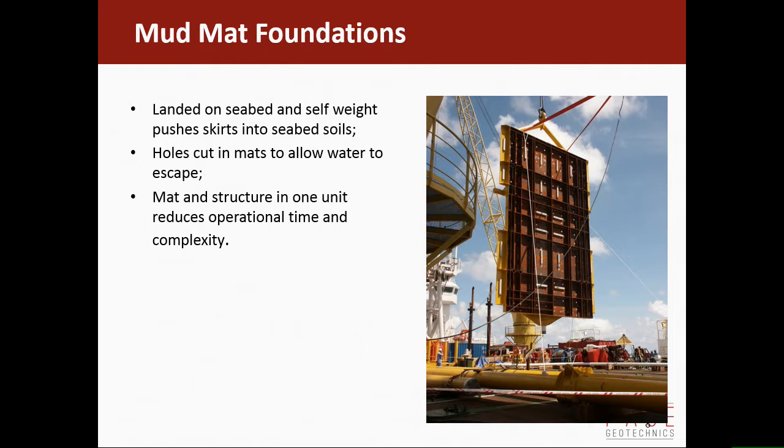that's an example of a mud mat foundation. That was a manifold we did, and it grew arms and legs. I think it went from 40 tons to 80 tons, and getting that to work on soft clay was really quite a challenge. Obviously that's the underside, and what the structural engineers often do is use the skirts on the underside to actually give it rigidity as well, so they're serving a dual purpose of penetrating the seabed, increasing the sliding resistance, and also making the structure rigid.